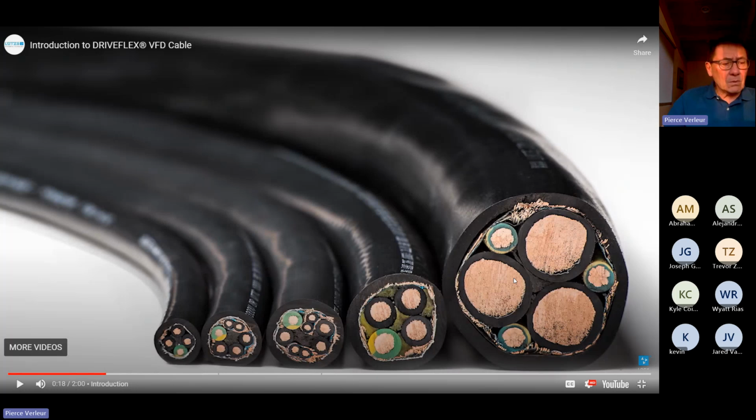Now, I don't know that a lot of people still just throw THHN in a conduit, let alone THHN for the power leads and your control leads in the same conduit. I think we're kind of getting the message across on that in the last 40 years. You don't want to run your control cables with your power cables. Shielding and separation is the rule.